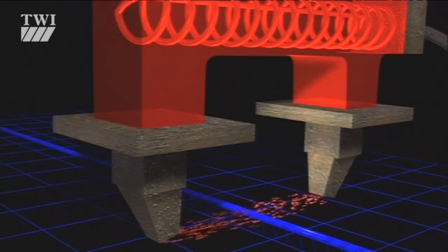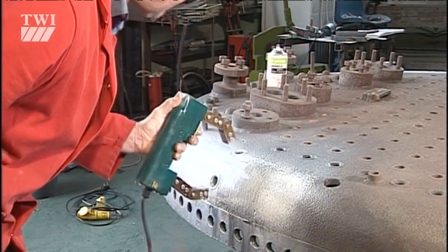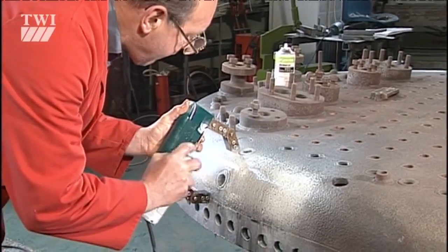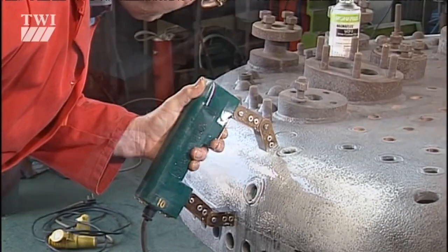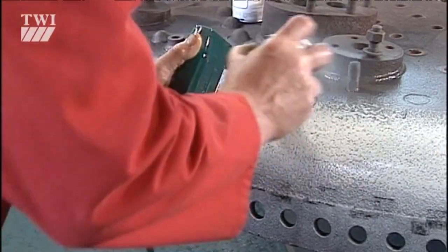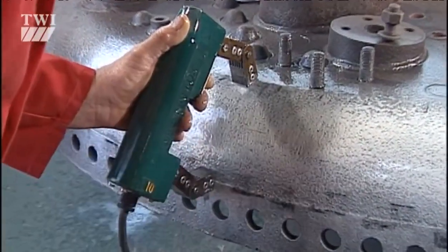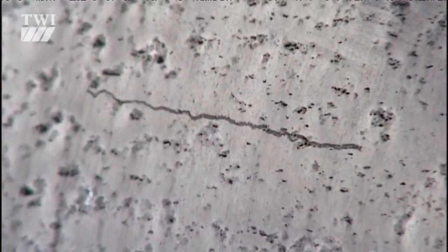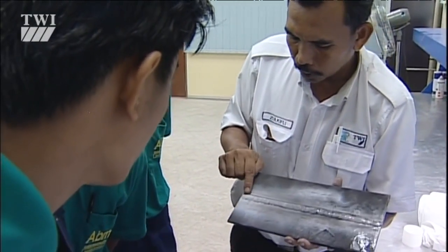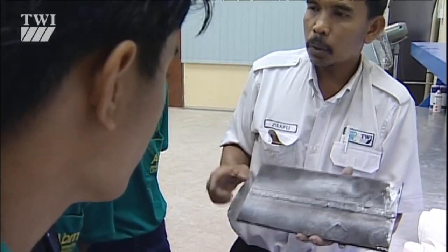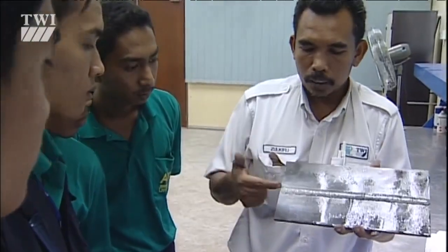An ink containing extremely fine ferrous particles is applied to the surface of a ferromagnetic material, whilst a magnetizing field is applied. Flaws cause leakage of magnetic flux, which creates new magnetic poles. So the ferrous ink particles are drawn to the site of the flux leakage field disturbance, and the inspector sees it. There are a couple of types of MPI: color contrast and fluorescent.